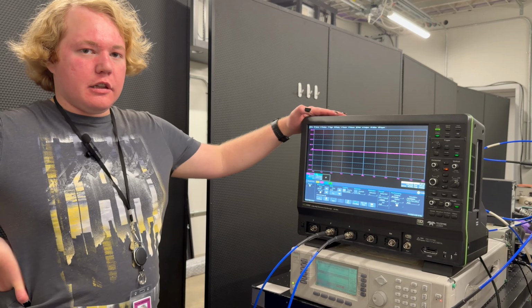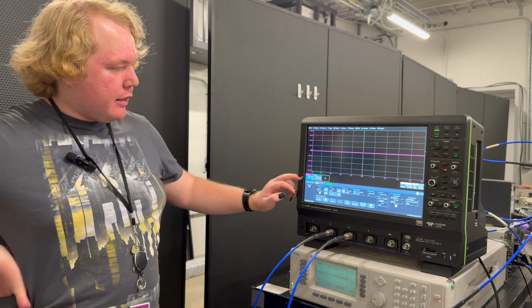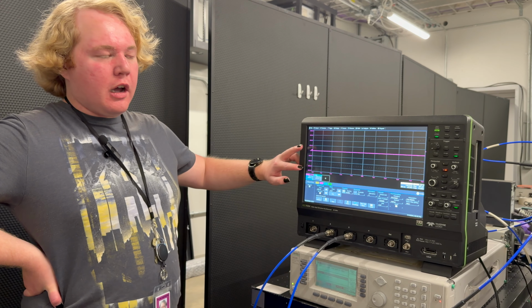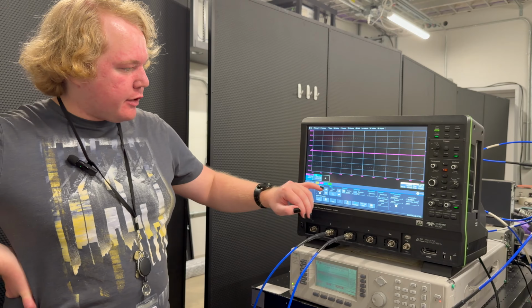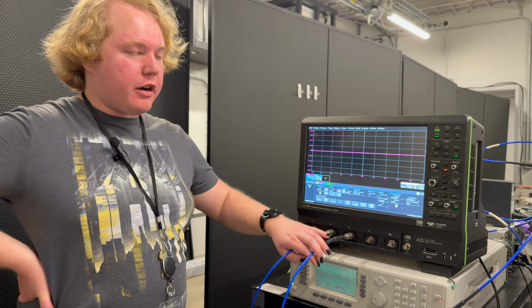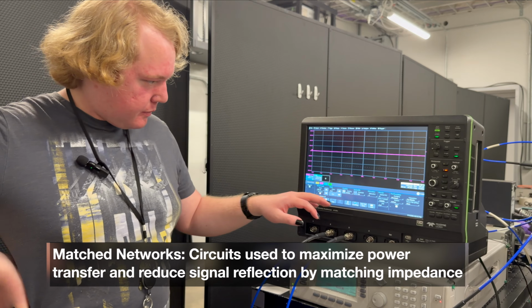So here we have the oscilloscope that we use to monitor the signals that are coming out of our CMS system. The settings we have typically are some voltage range between 1 to about 100 millivolts. As well, the coupling for all of them is on DC 50 ohms, specifically for the microwave circuit that we're using. Almost all of these are matched networks.